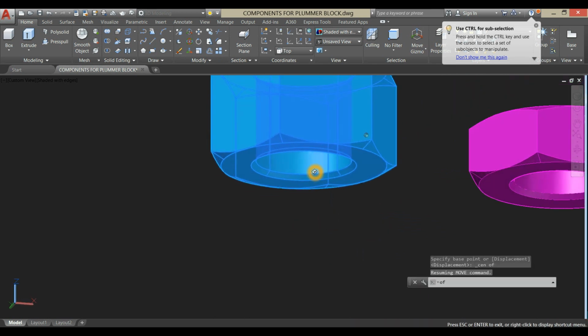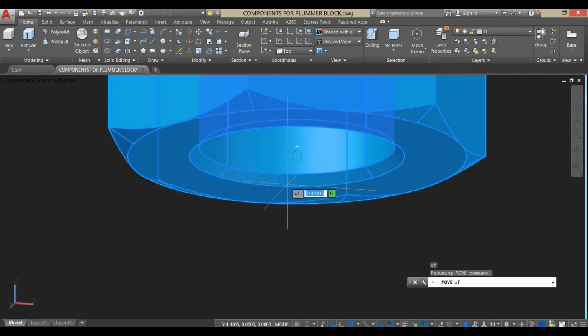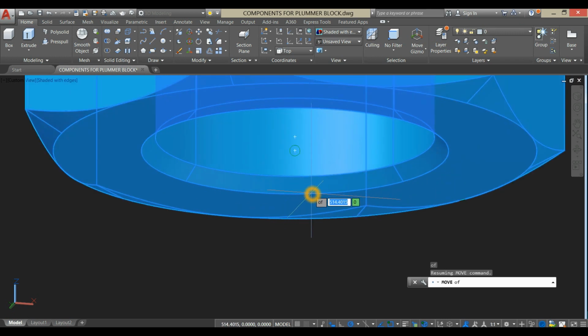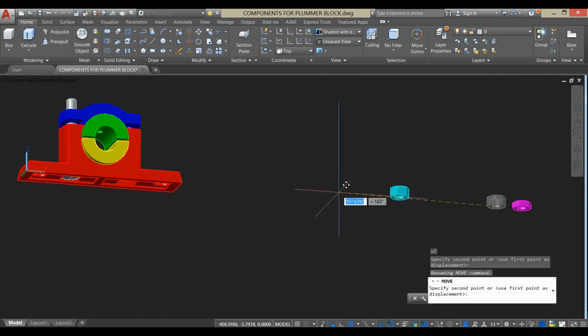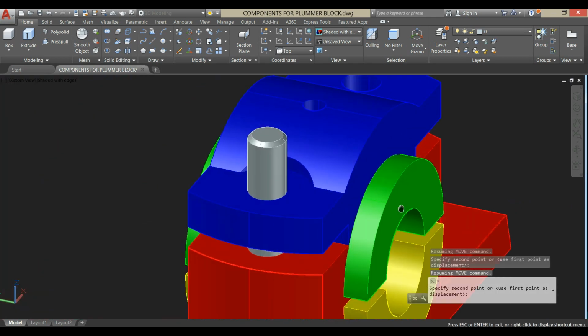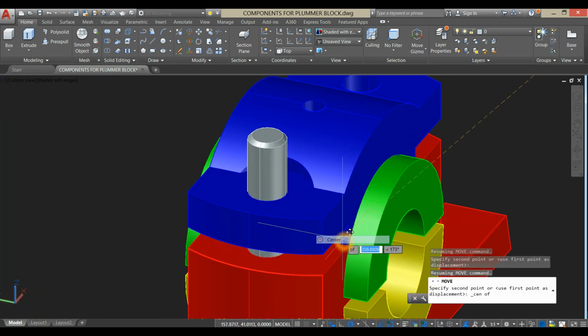And as you can see here, there are two layers of circle, and the cross signifies the center of a circle. So if you hover over this edge, it means this is the center for this edge. And you move over here, you can see the cross over there. So that's the center for this circle. So hover over here, click, and attach it. Shift right click, center of this one here, click.